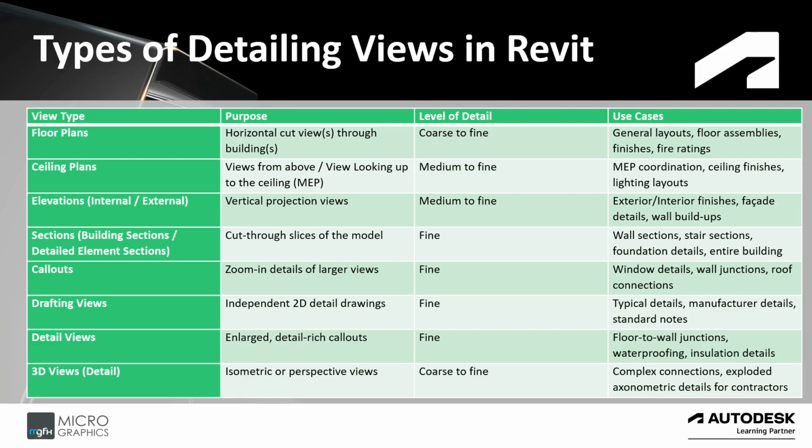You have callout views. It's a zoom-in detail for larger views on specific elements. It's fine detail. You have window details, wall junctions, roof connections, and so on. You are able to place a callout absolutely anywhere on the different views.